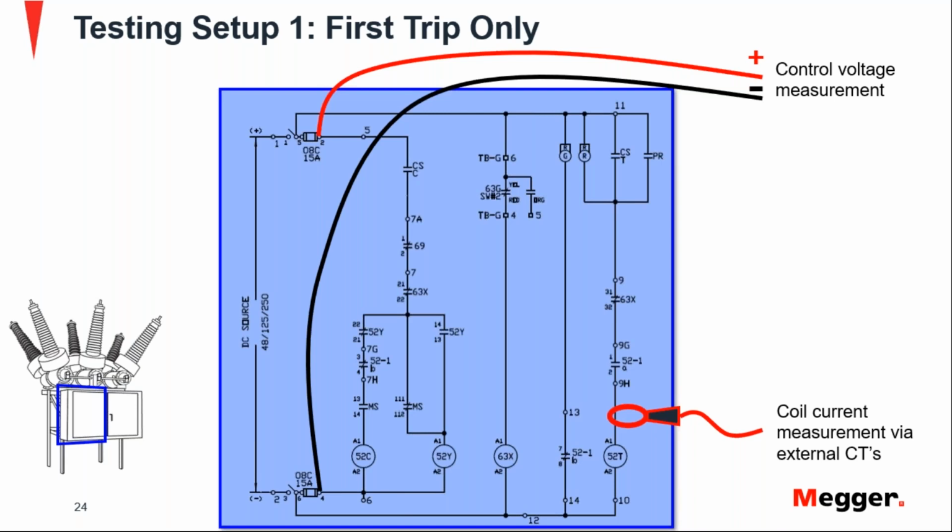positive and negative, and this is important because this gives you information about the actual DC signal from the control or from the substation. And one more connection that is needed is a trigger. So the instrument, the circuit breaker analyzer, needs to know when the breaker is receiving the signal.